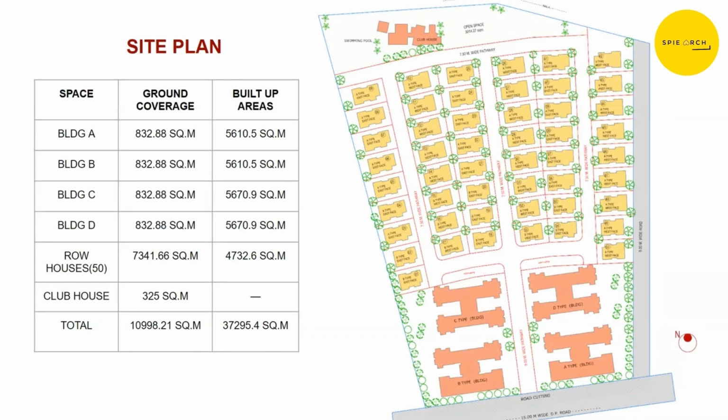Then, what are the contour levels of the live case study? What are the geographic conditions? Layout of the roads. In fact, what are your specific observations on the layout of the roads which they have designed in the live case study which you have done? So the width of the road is sufficient for 2 cars to pass, and a proper turning radius is also provided for each road. No, basically, it is according to the rules and regulations, according to UDCPR. Because unless they provide it according to the rules, they will not get the permission. Nobody will get the permission if it is not according to the rules.